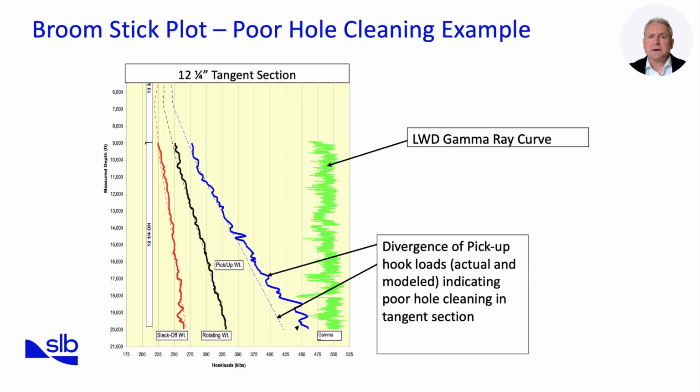Here, the actual measured pickup line deviates above the planned curve, while slack-off data also diverges. This divergence is diagnostic of poor hole cleaning, especially in the tangent section, where cuttings beds increase drag and reduce effective hole diameter.